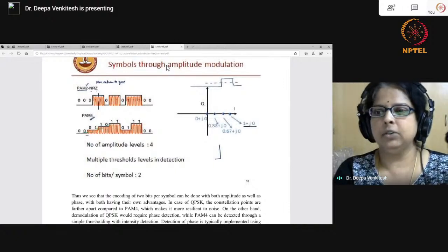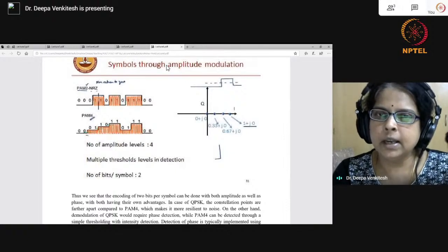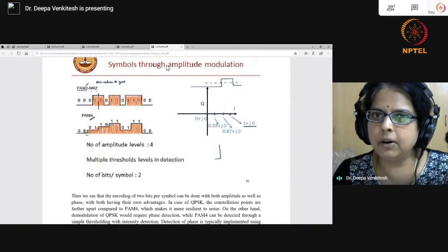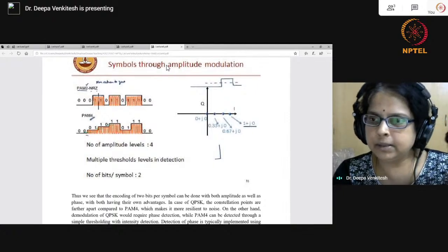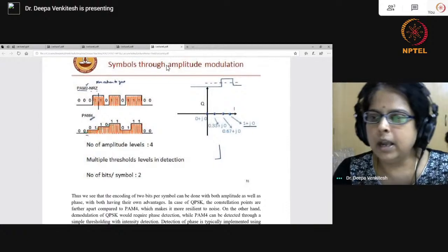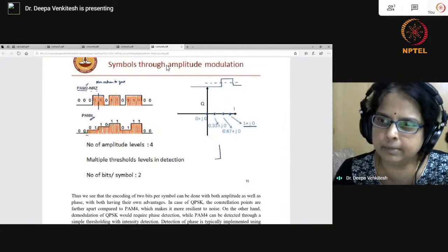Simply because coherent transmitters and coherent receivers are typically available for 1550 nanometer. So I would recommend that you take 4 channels of around 1300, 1310, 1320 and so on, and modulate 25 gigabit data on each of them. That should be the better solution.